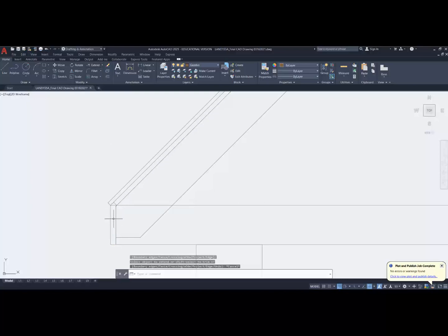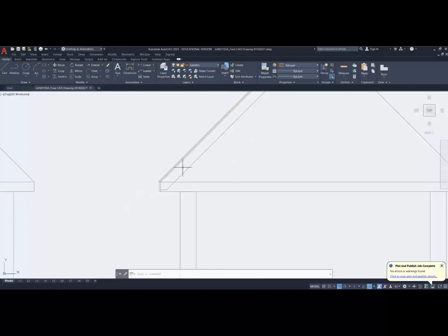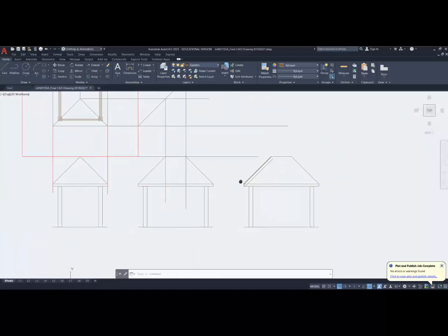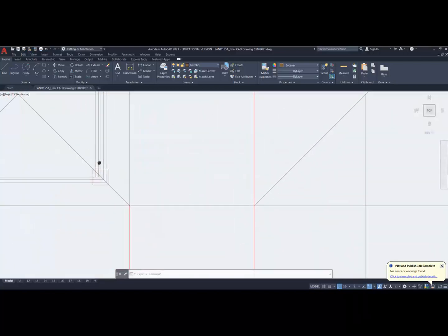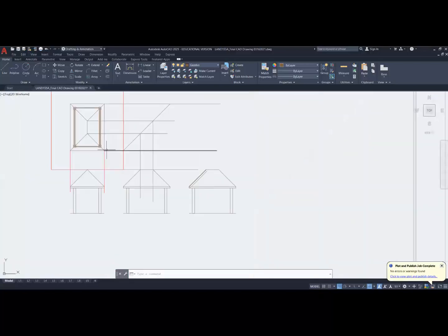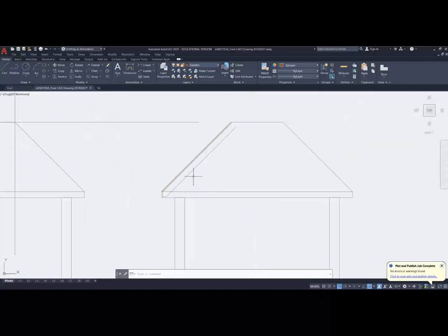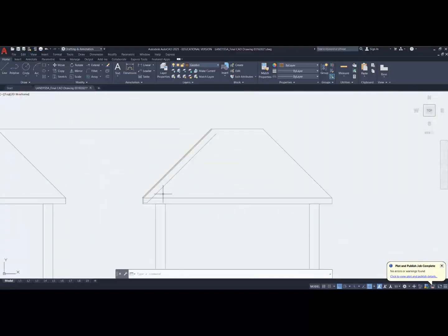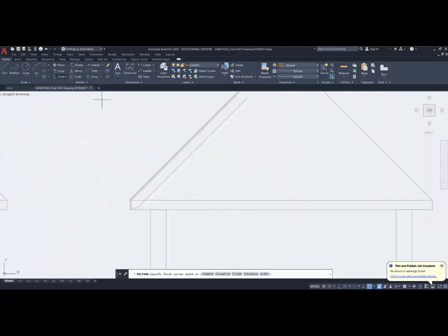The actual joist itself has this unusual shape to it, the end cuts, and this is at a 90-degree angle. This will sit on top of the beam. So we're drawing the long edge, and we're going to see the short edge of the beam. But I'm going to draw the bigger edge of the beam here. So it's 4-ply 2x12s. I believe that's what we're using here, 4-ply 2x12s. So I'm going to draw that here, and you'll be able to see it.